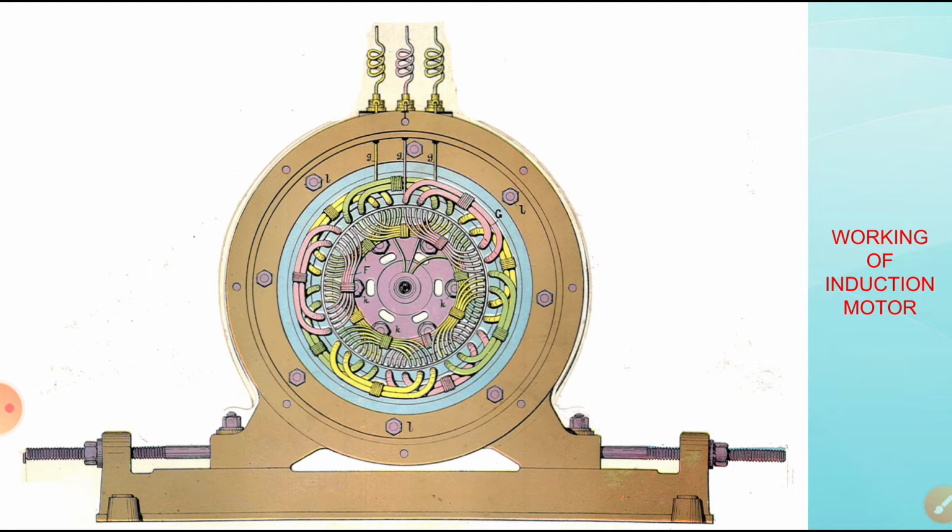As you know, in our domestic use, if the bore is above 500 feet deep, then we prefer a three phase submersible induction motor. For 200 feet or 100 feet, a submersible single phase motor is enough to drive the bore water to our overhead tank. This is a good example.